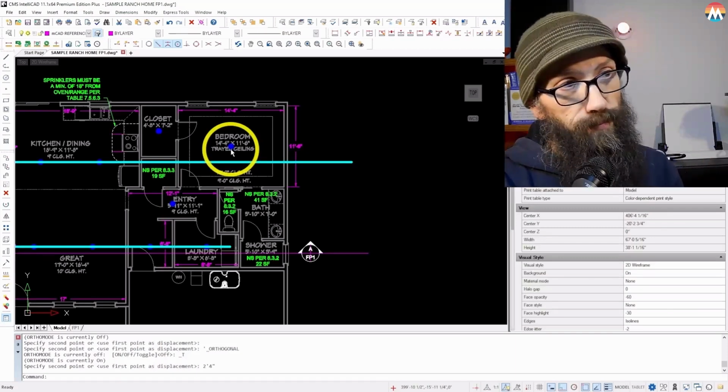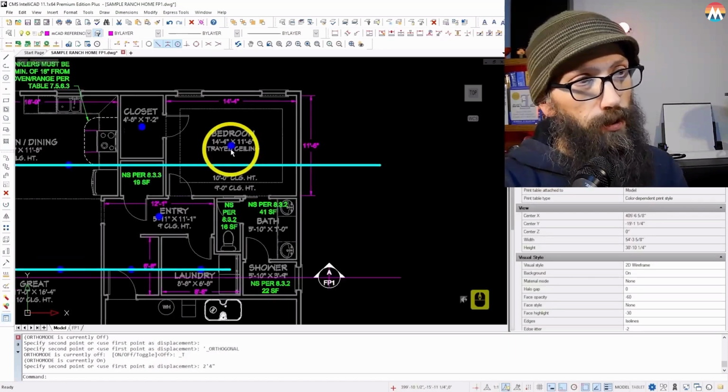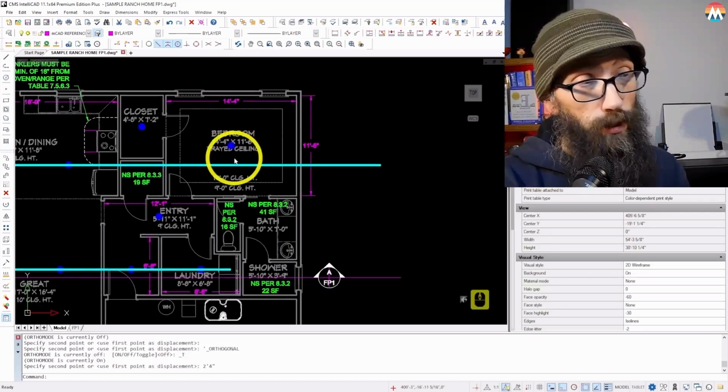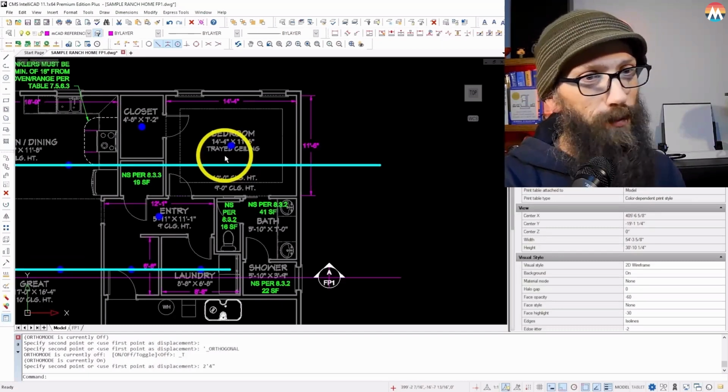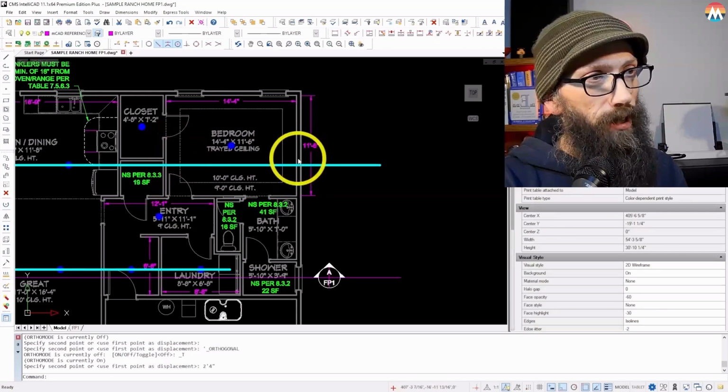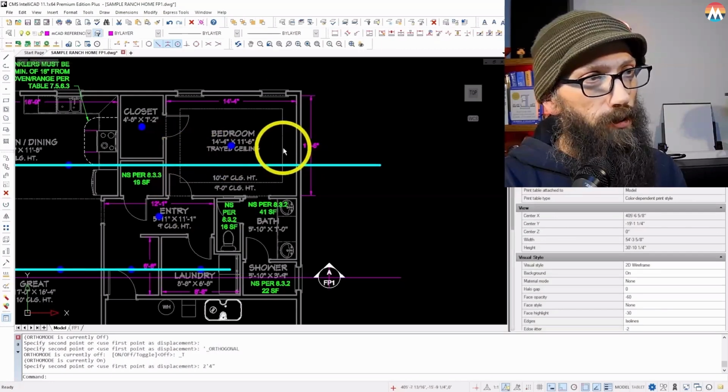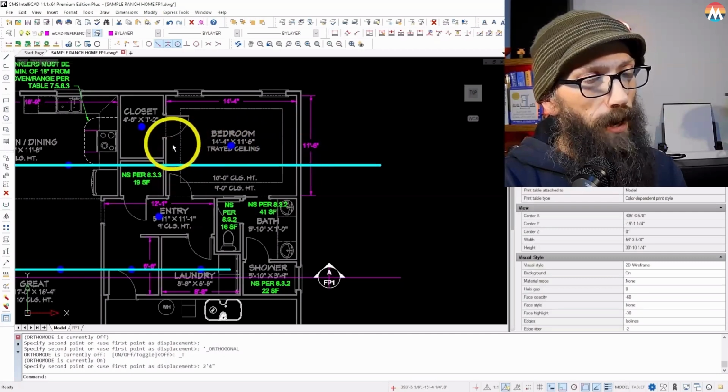We could cover this room with 16 by 16 spacing by putting a head right in the middle, but there's going to be a ceiling fan there or some sort of light, chandelier, whatever. So because this outer ring is lower, I'm actually going to do 2 heads to straddle this fan that they're likely going to have there. And I'm going to put each head out in this lower part of the ceiling.